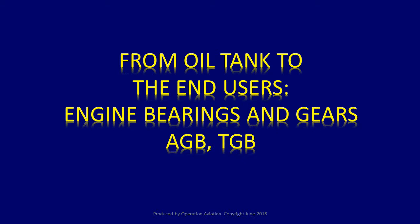All right, so here, what do we have? What's the general idea, and what parts do we have in this thing? Well, for one, we have to have filters. There's different filters. We also have a clogging indicator transmitter, because we want to make sure that that is being indicated in the cockpit, right? So we need to have that clogging transmitter when the oil filter is indicating it's clogged. We want to make sure that we know that. And there's also the bypass valve. You got a pressure gauge also, and a temperature sensor. And we'll talk a little bit more on the temperature part as well as pressure.